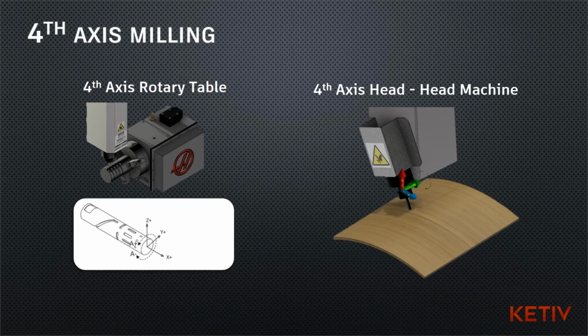Now you don't just have a 4th-axis rotary table. You do have something along the lines of this diagram as well. The specific name for it, I'm not too sure, but you do have it. That's where the head of the machine has the ability to tilt, right? So it is going to be rotating some degrees about the y-axis. This is important because in your post, if you are the one doing the post modifications, you have to write that down in the post or take note that the head is the one that's going to be moving and rotating about the y-axis.